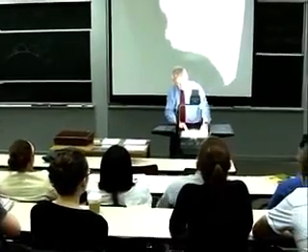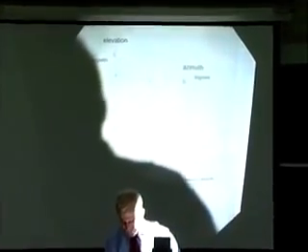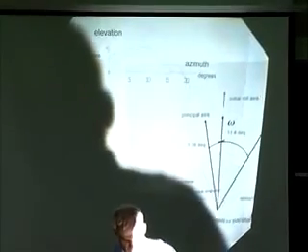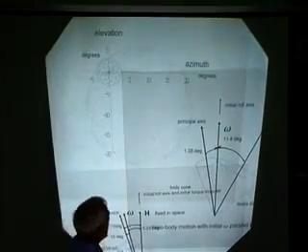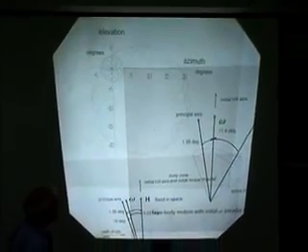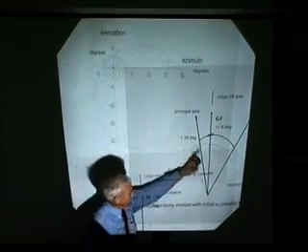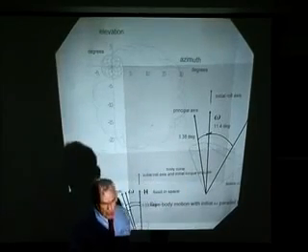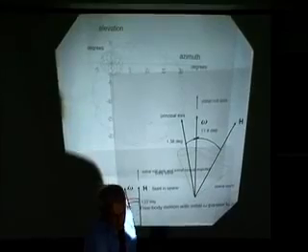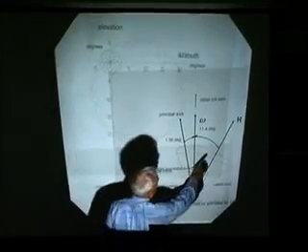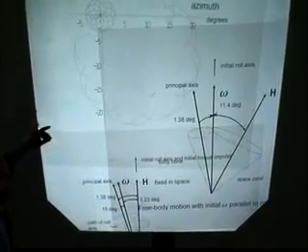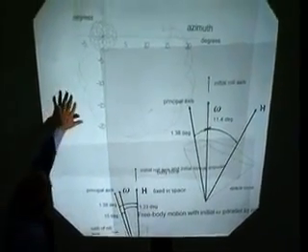Size of the space cone and body cone in the two problems, and now you see the exact solution in the two problems. You can see their relative sizes. The initial angular velocity for the exact numerical integration with the unequal principal axes, you got a motion with the angular momentum vector 11.4 degrees away.